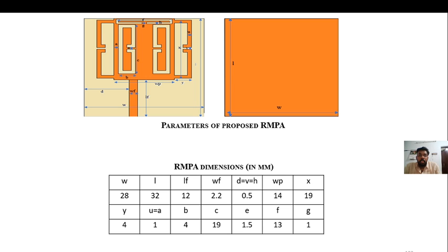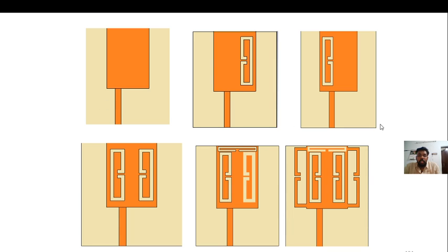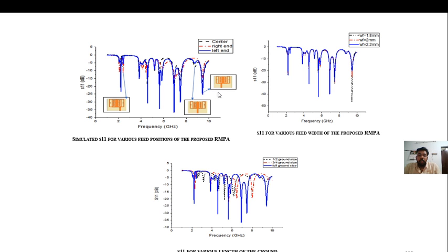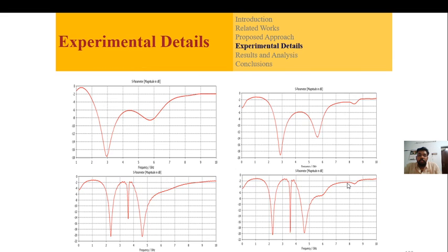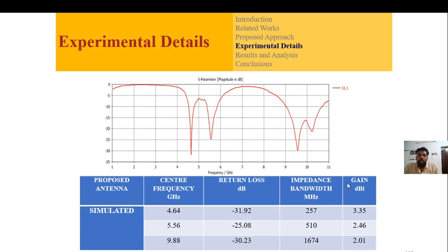And this is another antenna design. Here I am going to have 6 stages of evolution. The first stage is a simple microstrip offset feed, and then the design complementary split ring resonators, and split ring resonators have been introduced at the end, and I can achieve 8 bands. This is another output, and this is the metamaterial structure.